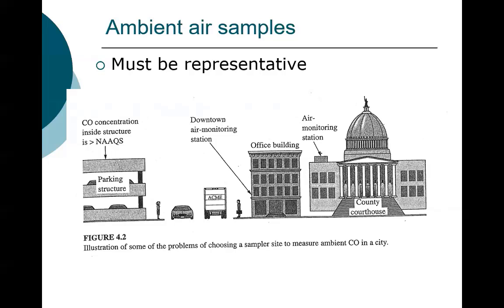Do we put it in the parking lot, in the parking structure? Do we put it on top of the courthouse? Do we put it somewhere, let's say, right above this window here? Where do we want to put the carbon monoxide monitor? By the office building. So why would we put it by the office building? Well, with carbon monoxide, we're looking at what people are breathing. What's the likely exposure? So you want it close to where people are located.